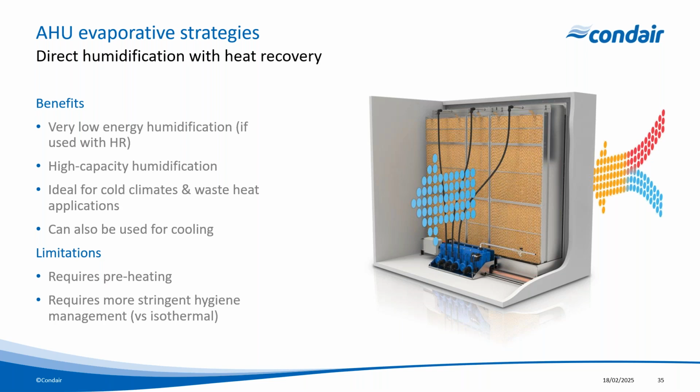So now we're going to look at our final strategy here, which is using evaporative technologies to increase humidity without necessarily using it for the objective of cooling. As we saw earlier, when we looked at the world map, this type of humidification is very beneficial when used alongside free air cooling systems in colder regions, where without any proactive moisture addition to the system, the indoor relative humidity would likely be extremely low.